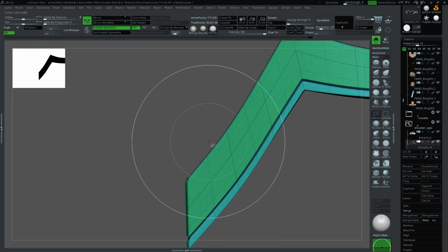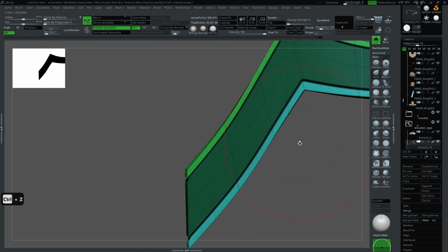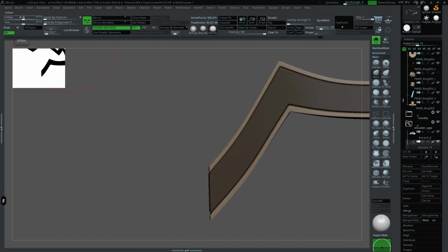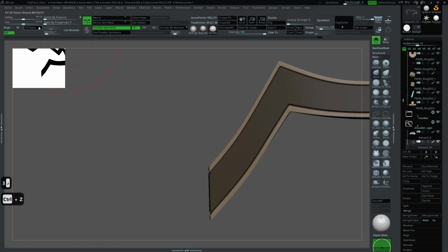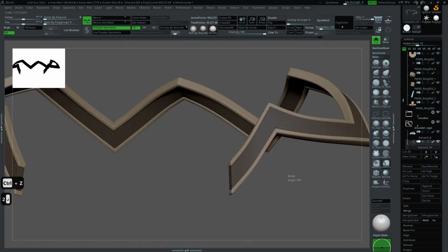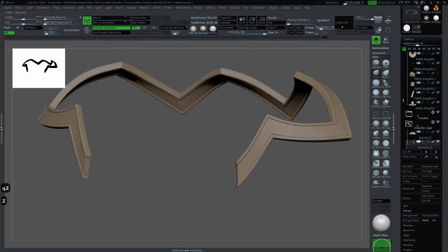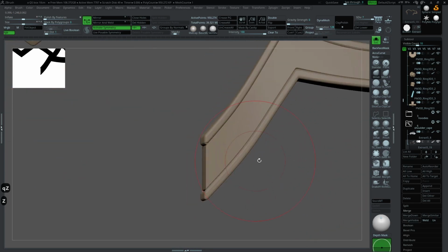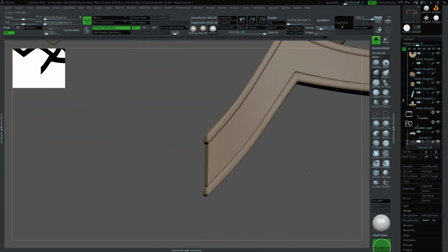So now I'll select this part here and the down part as well, and then I mask, unhide all, and can just inflate it, put it 3 like this, or maybe too much, just put 2. Now we have these edge details like this. So there will be shapes like this, but this should be fine.